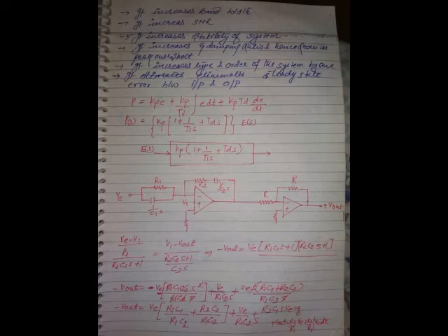Now listen here. What is the effect of this controller on the rise time of the system? Rise time is reducing, yes or no? Because it is improving the speed of response, it has to reduce the rise time. Only in an underdamped response you will find peak overshoot. This is the peak overshoot, this is the rise time. As the rise time reduces, what should happen to peak overshoot? It should increase, yes or no?